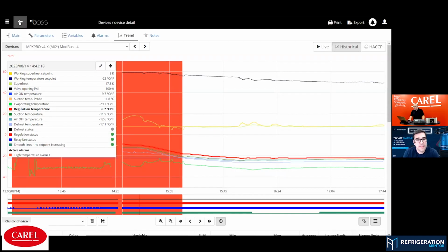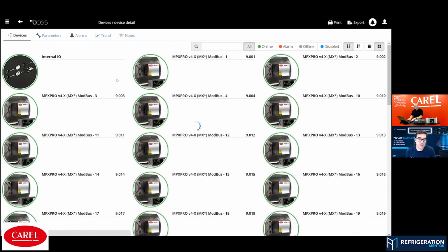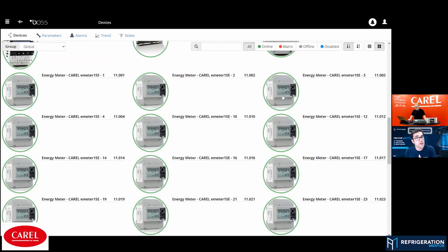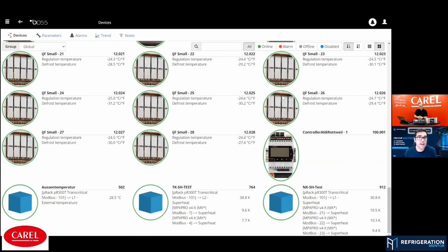I just want to add to that, and that's a skill, right? If you're a technician out there and you've got a few years in and you want to learn, you start with the trend graphs and stuff like that. The energy optimization is going to come with skill, like years of experience working at this. Timo is an expert at it. So it's looking at these graphs, and it does take years. So don't get frustrated if you're working on a system and you don't really understand, because it could be one of many things. It could be that the store itself doesn't have good conditioned air. The humidity could be super high, or the temperature in the store could be really high and causing this. So on the energy optimization side, it takes years, and you just learn from people that do it, just like Timo.